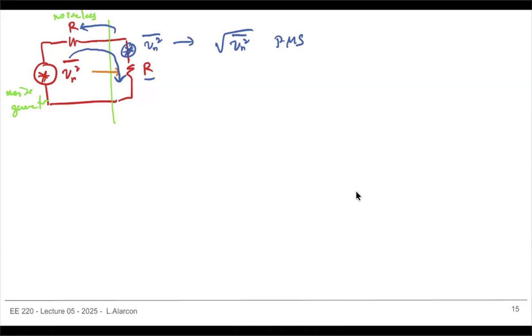And it turns out that, okay, if I have a resistor and I have a voltmeter or whatever, right? So a DVM that you have in the lab, it could be digital or whatever. That thing is going to, if it's an old style milliampere movement, that thing is going to deflect because it actually measures the RMS voltage of the noise.